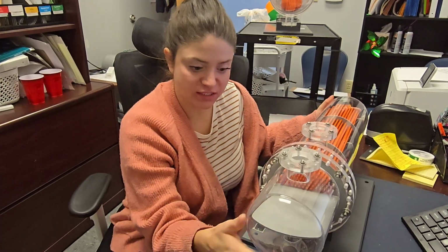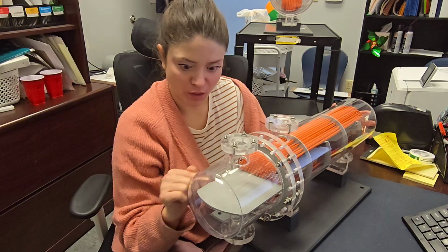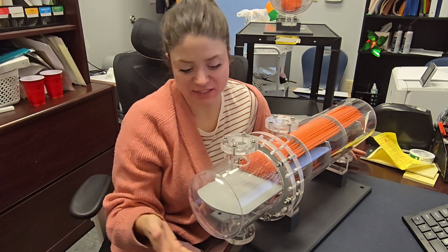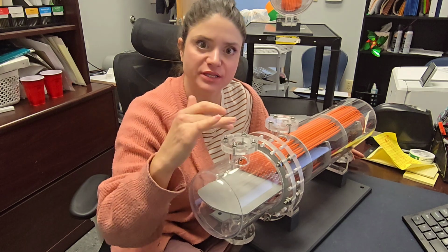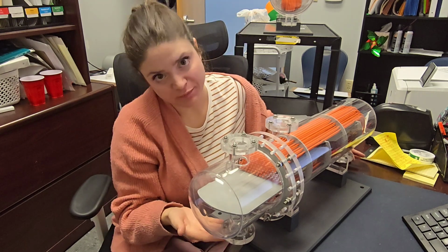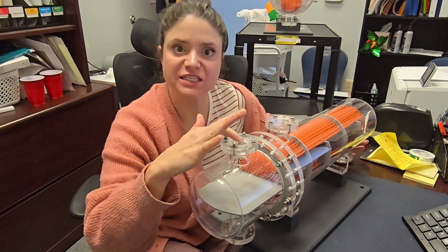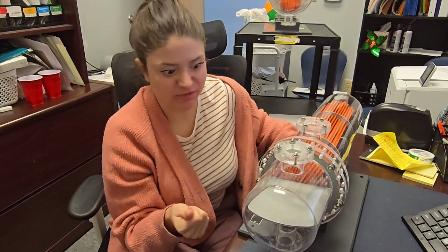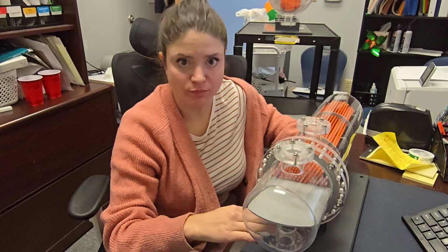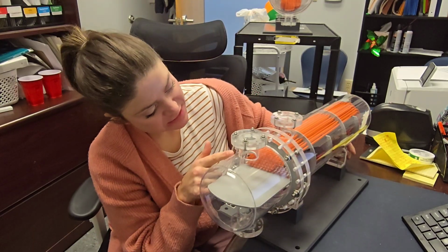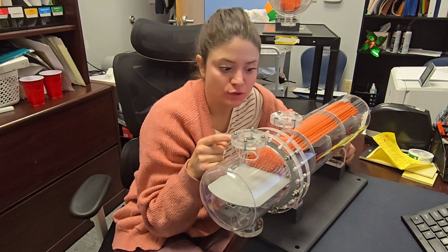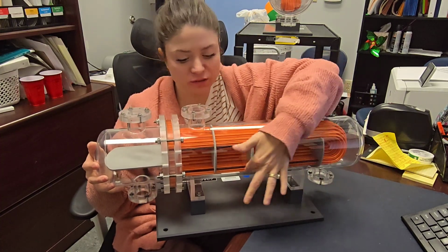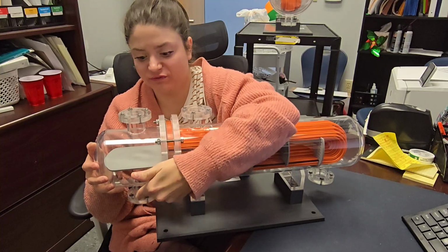And this thing right here, this is your pass divider. So for your tubes, let's say this is the inlet. It can be either way. This could be the inlet and this could be the outlet, or this could be the inlet and that could be the outlet down there. But we're just going to go with this is the inlet, okay? So it's going to come in. This pass divider is going to prevent it from going to the bottom. And it's going to go through the hollow tubes, go all the way around, right? All the way around. And then it's going to come out down here, or vice versa.